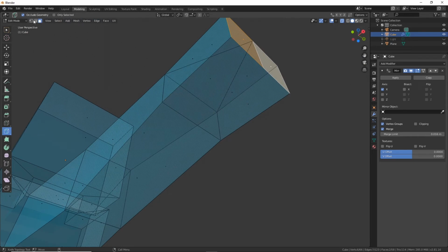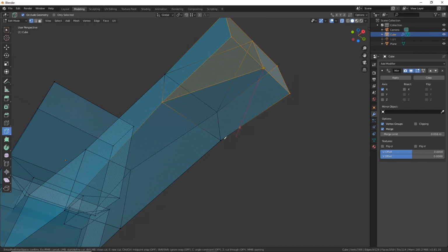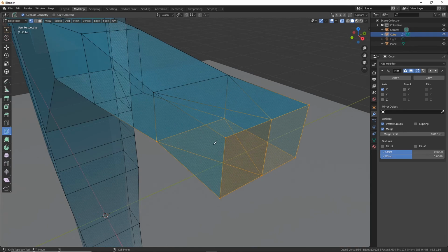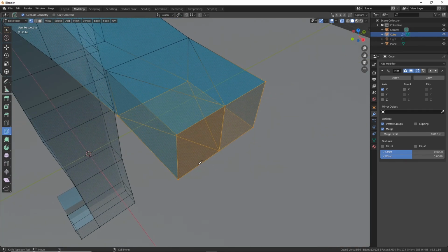Let's go ahead and turn on select by point, and then turn on magnet. This is a snap tool to the vertex. So then I can just click and click, right click, click, click, right click. So now I've got 2 fingers here, and I can just do the exact same thing to add the other 2.